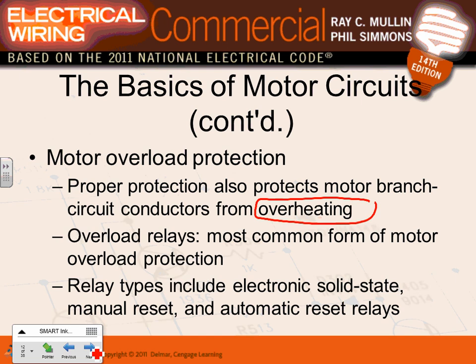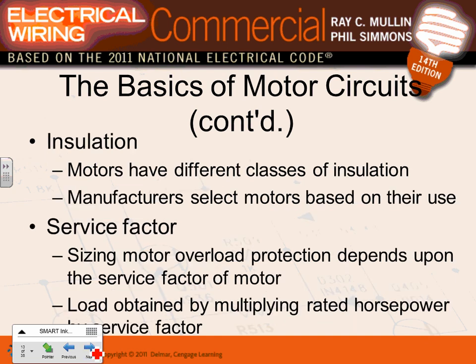The common forms of motor overload protection are overload relays. These are the electronics or the heaters. I know Jerry, when he comes, showed you all these relays that they use, some with manual or auto reset. So typically two types: the heaters, the ones that heat to disengage the circuit, and the electronic ones, which have a relay. The electronic ones, you can manually or automatically reset them.